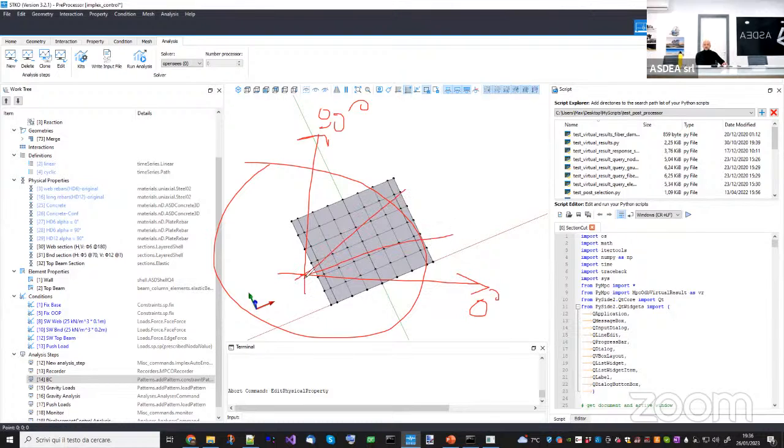We typically use 4 subdivisions. Now imagine you first load in this direction, so you are damaging either compression or tension. I apply the same concept on both. You have a stress that goes in this direction, so it damages along the history, let's say at this point, to a damage of 0.8, for example.